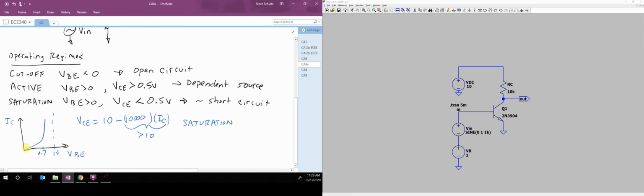Now, coming back over here, it would be easier to control if, when this turns on, it's linear, so that I can change this voltage a little bit and it doesn't have that exponential response. So I'm going to come in here and add a resistor in. Let's just put in a big resistor, 100 kilo ohms, so that I get a more gradual response.